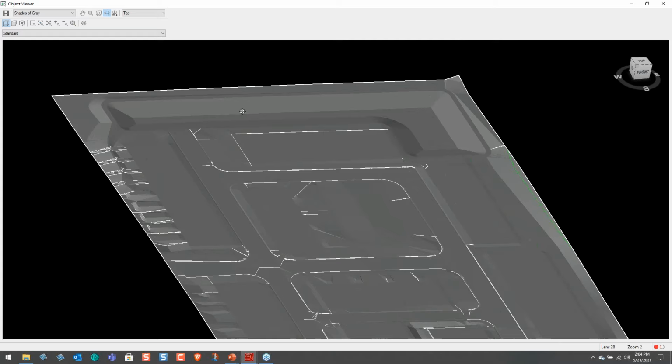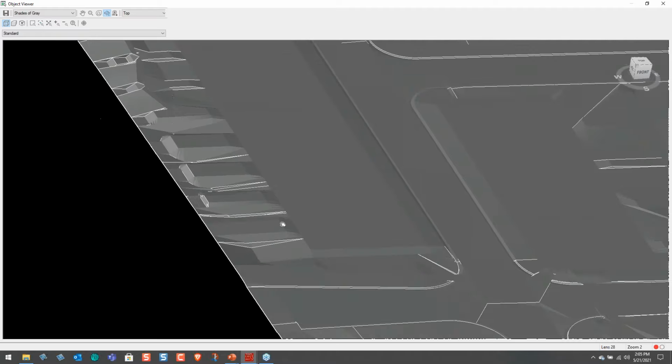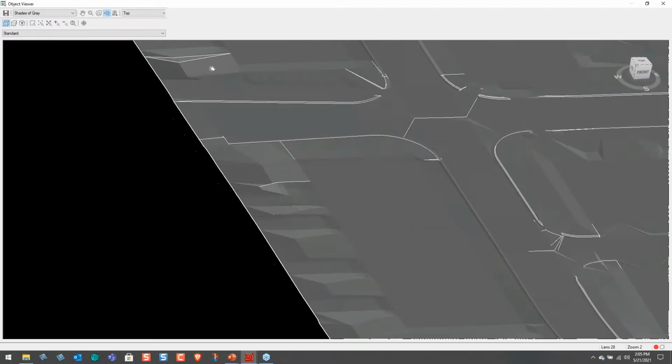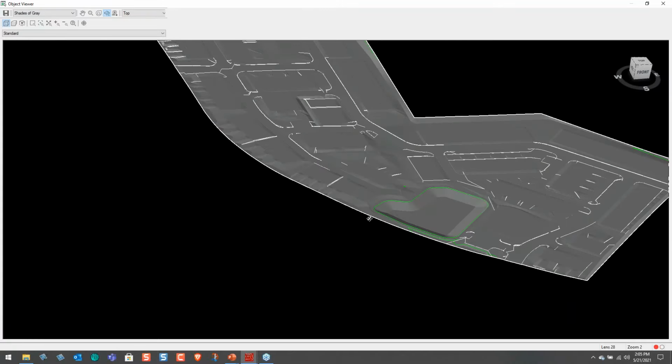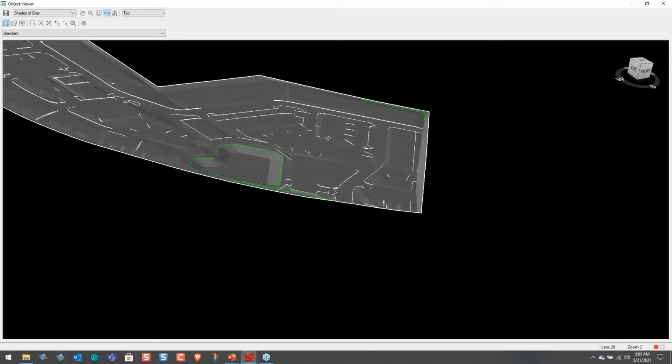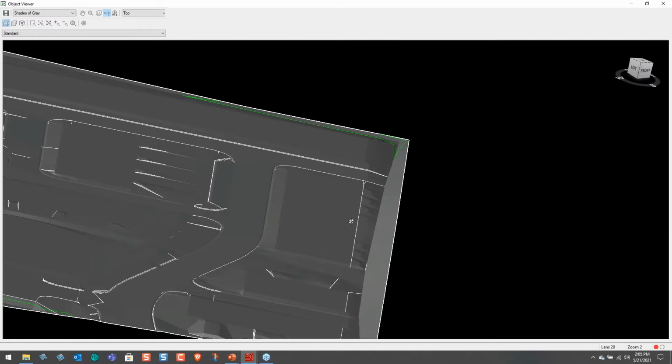We've got a couple of ponds in this project. Here's the pond. I used ditches for this entire project. There's a lot of cut, but we avoided retaining walls and other things like that. In fact, the developer told us we saved him about $300,000 worth of excess quantities, because the site is in a lot of cut. We've got a ditch going this way, and a bunch of sidewalks going into the buildings here. We've got a ditch running through this way, and another pond that splits the site as far as the drainage goes. Through the back side, I've got a ditch running the whole way. Yes, it's a steep slope, but it does work.